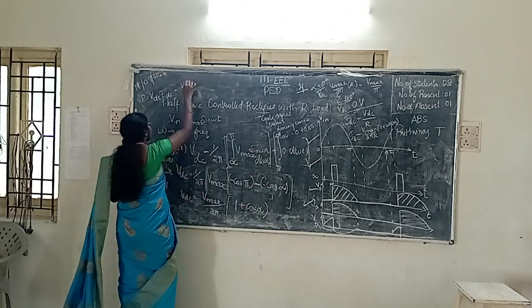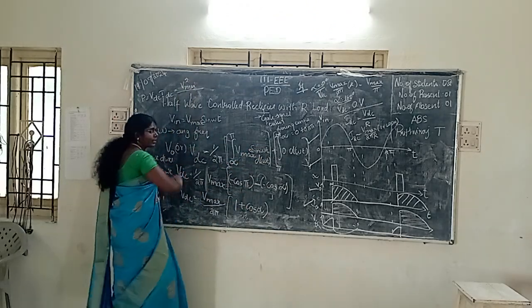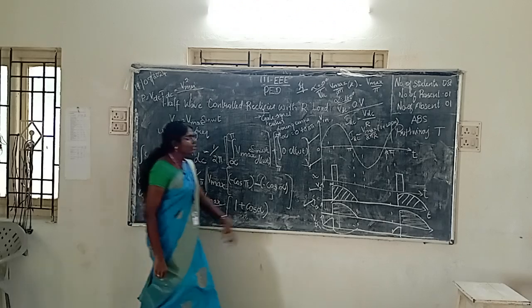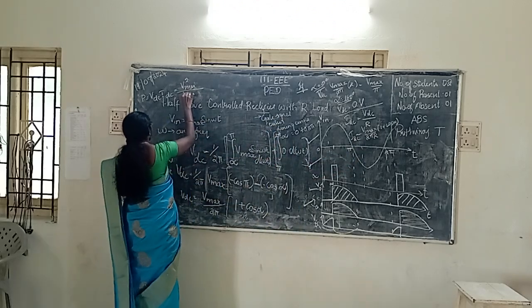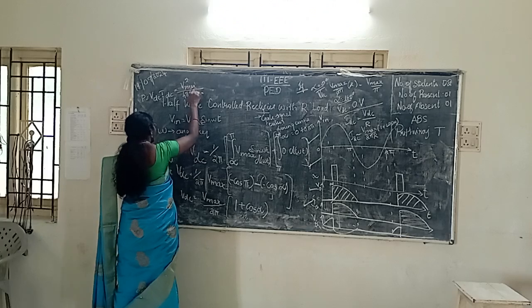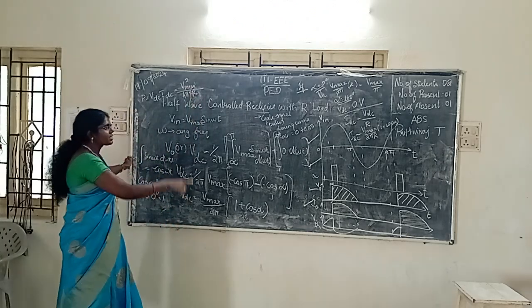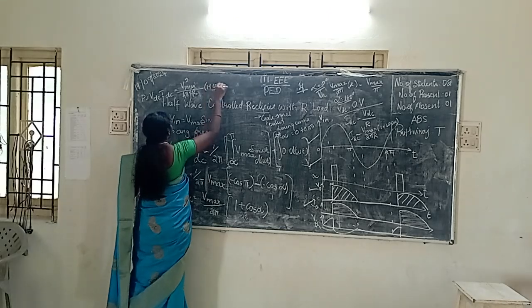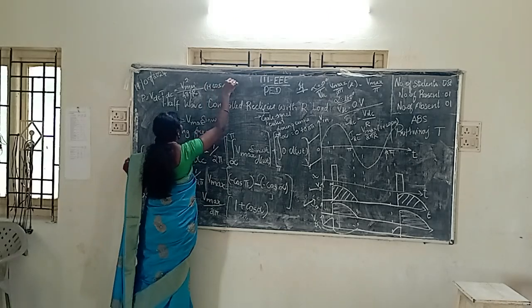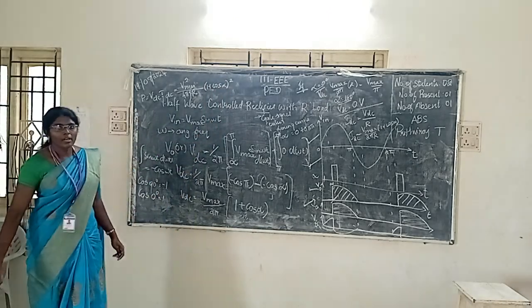So we can write it as V max square divided by 2 pi times 2 pi, which will become 4 pi square. Who is going to be the denominator? R. And 1 plus cos alpha will become 1 plus cos alpha the whole square. That is the power delivered.